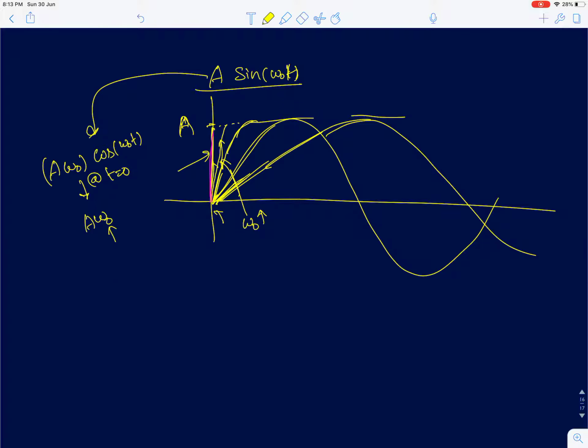The reason we are going for infinite frequencies is that we normally give a step input as one of the most commonly given inputs in circuits. When we give a sudden step input going from 0 to V_x, the system at t equal to 0 will think that an infinite frequency sinusoid has been fed to it at t equal to 0 alone.